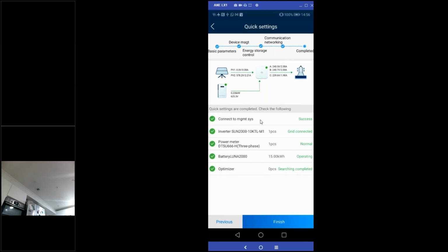Going back to peak shaving though, if you have different tariffs over the time of day, you can actually use time of use and make sure that you buy cheap energy at night, and when the morning comes and you have a peak in the morning, then you will draw from the battery. Yes, not exactly, but in that sense you can actually use it as peak shaving.